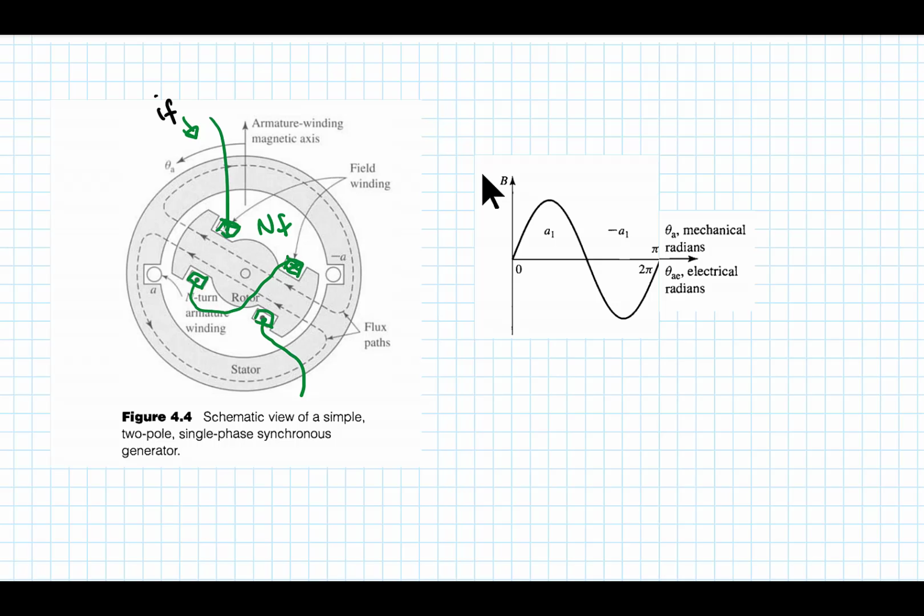If we consider that because of this field, we have a flux that is created, following this magnetic circuit, splitting up in two on both sides of the back iron here, flowing in this direction, taking the right-hand rule. We could see that effectively we've got a north and a south pole that's created.